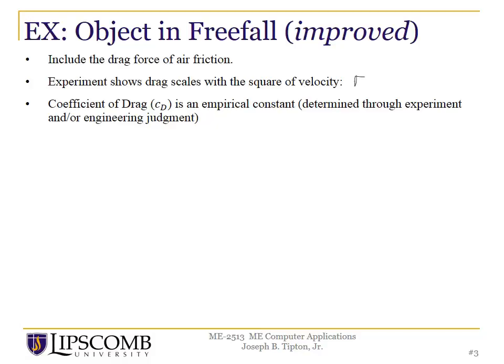Mathematically, I'll say F sub d, the drag force, equals c_d, a constant, times the velocity squared, where c_d is our coefficient of drag, and that is an empirical constant, meaning it's determined through experiment, curve fitting, for instance, to data, or engineering judgment.